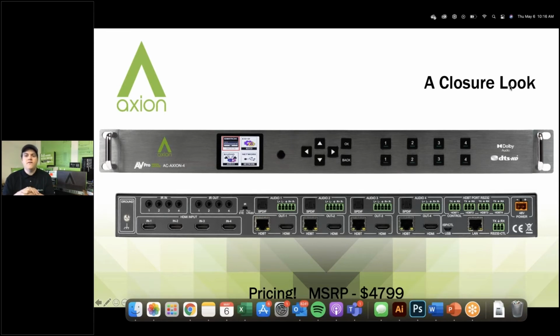And then I have a question from Sammy. Can it do 4K 120 hertz? This is an 18 gigabit per second matrix switcher. So that's a great question, Sammy. But it just has to be under the HDMI 2.0 specification. Now, as I said before, this does have a larger backplane, and Sammy may be playing to that because there are actual ways that we can do that, but we don't want to just say that that is a standard on this right now, 4K at 120 hertz.